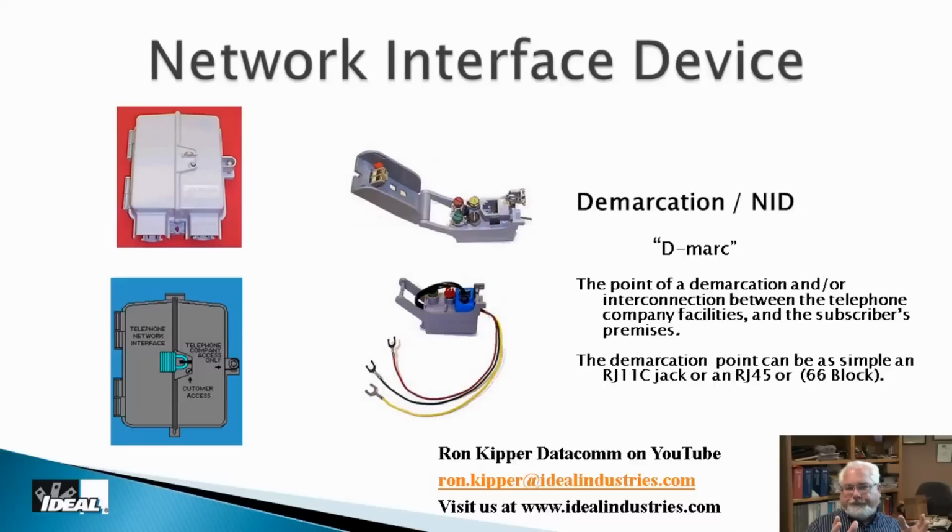And in the old days, we would come out of this box and go into the first outlet on the first floor and splice that cable, go feed the next outlet, splice that cable, and go feed the next outlet. And that's referred to as daisy chaining of cable, which we typically don't recommend today.